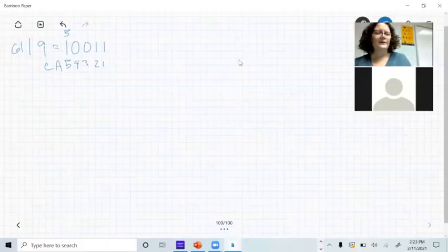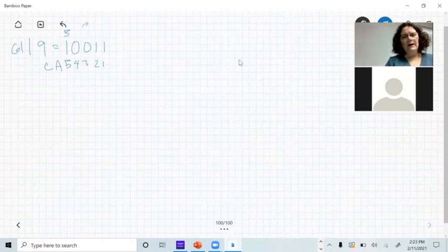Okay, now we're recording. So for number 3, for column address 19, 19 decodes to 10011. And each one of those bits is going to correspond to a column address. So the most significant bit is column address 5. Next one's column address 4. This is column address 3, column address 2, and column address 1.